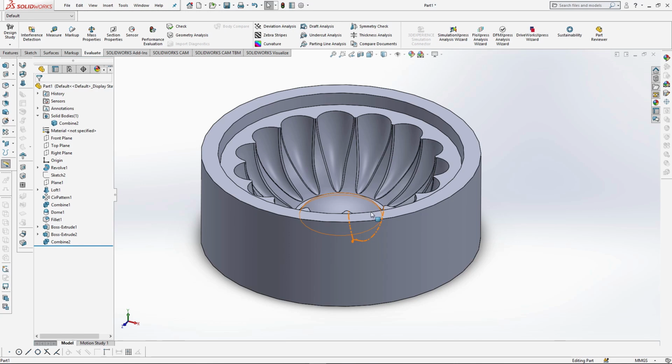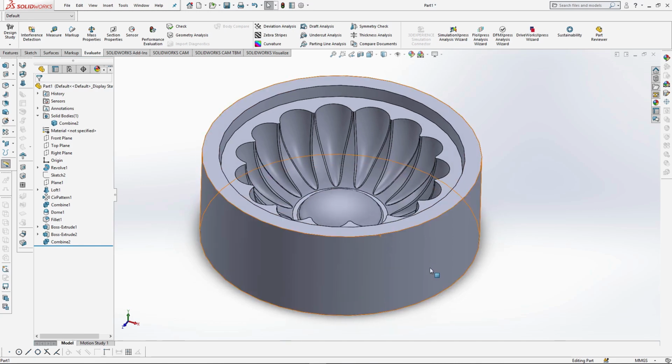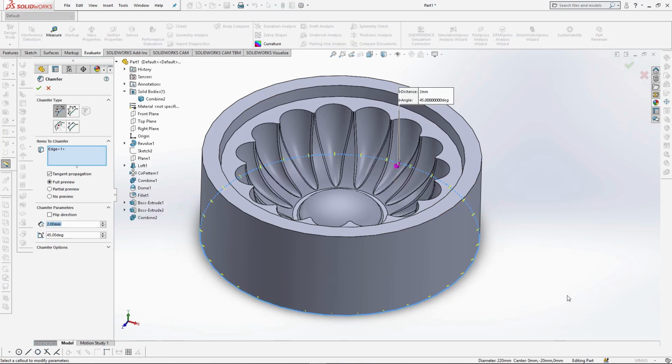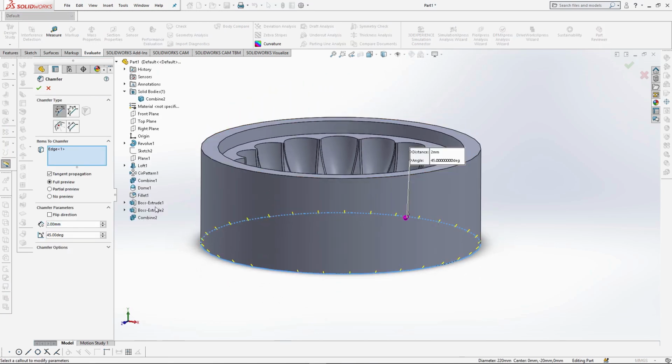To complete my mould, I'm adding the finishing touches. Selecting the bottom edge of the mould, click the chamfer icon. I'm adding a chamfer to the base of the mould for practical reasons. The chamfer makes it easier to pick the mould up from underneath. When the mould is full of clay casting slip, it is very difficult to pick up. It also minimises the risk of injuring fingers. For this chamfer, I'm changing the dimensions to 10mm, keeping the chamfer angle of 45 degrees.